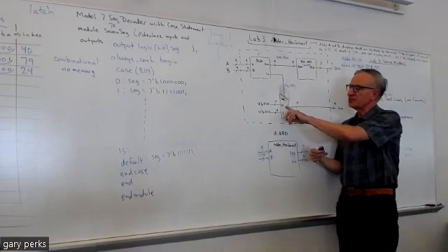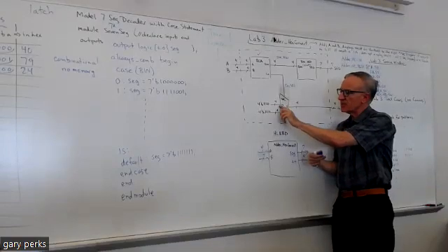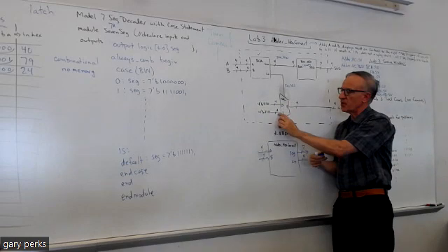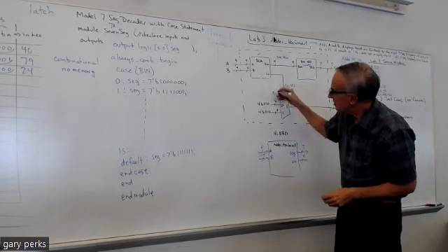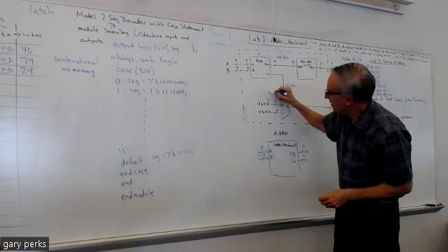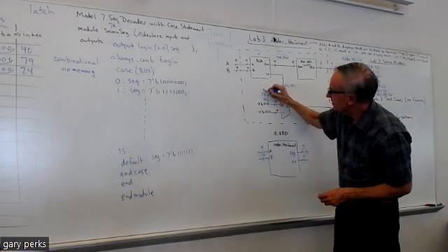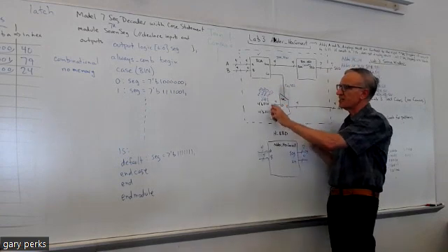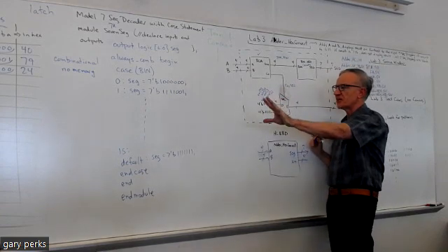Okay. Well, do you see why input 0 of the mux has this data 1, 1, 1, 0, and why this input in the mux has all ones? See this bit right here, that's the AN 0 bit. This is AN 1. This is AN 2. And this is AN 3. So you see, this is the AN bit for the furthest to the right display.